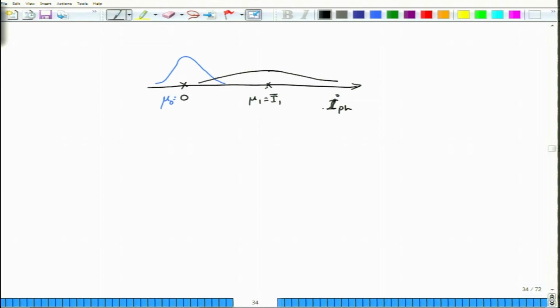photocurrent that you would obtain, the amplitude of the photocurrent, and on the y axis is of course the probability itself. Okay. So, you can clearly see that if this I1 is very large compared to 0, then these two tails of the distribution curve will hardly overlap. But when I1 is brought closer to 0, because you are not putting out enough optical power, remember I1 is directly proportional to the received optical power P1.